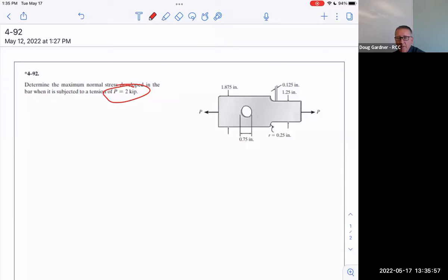The maximum stress is going to happen. Remember, stress is the force divided by the area, effectively with this K value, this concentration value, this multiplier, because notice we just said a second ago it was 2.2? That's a 120% increase. That was a massive change. That wasn't just a tiny little increase, it was massive. So we're basically just multiplying it by something to make it larger. So this would be the same problem. It's just that instead of not knowing what N was, we're not going to know what the top was, right?